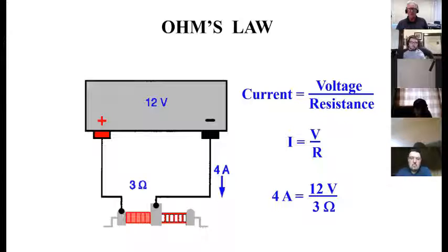Now you got a problem. Again, a lot of times you just need to be in a ballpark with stuff. So don't ever approach a problem too much in detail. Don't get in that thing about you can't see the forest for the trees. Before you start digging into a lot of prints and really doing the heavy head work, step back and make sure nobody kicked off a piece of conduit or a fork truck didn't knock something off, a limit switch or something off that's causing something not to work. But sometimes you do need to calculate numbers, and that's what Ohm's law is good for. What's more important is what I've been trying to get across to you, that current is the result of the interaction between voltage and resistance.